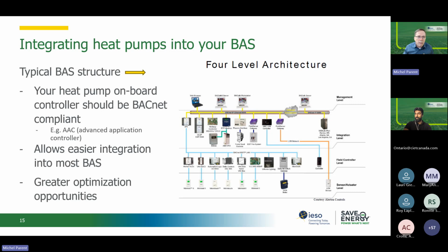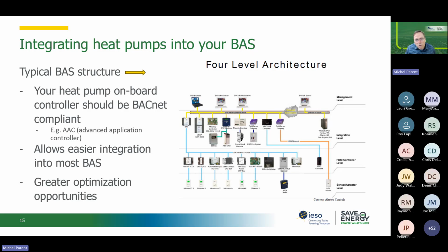You want to select a heat pump that will be BACnet compliant, and it will have what's called an AAC, an advanced application controller in BACnet terminology. It resides on the field level of your BAS. It will give you much greater optimization opportunities.